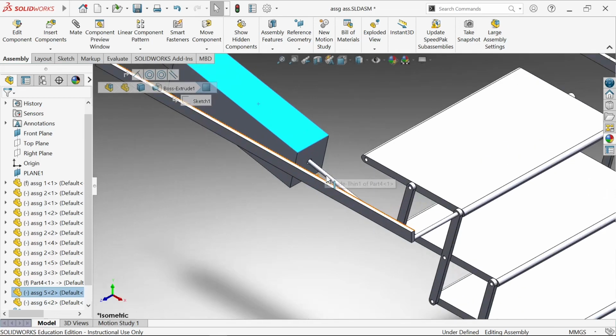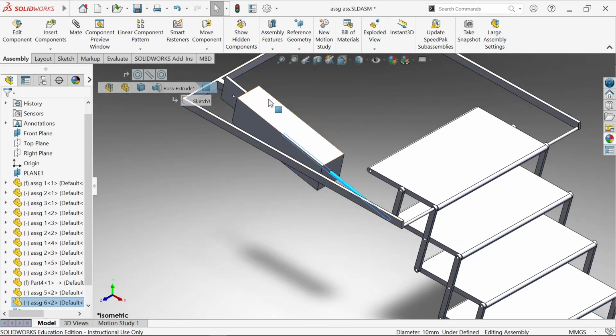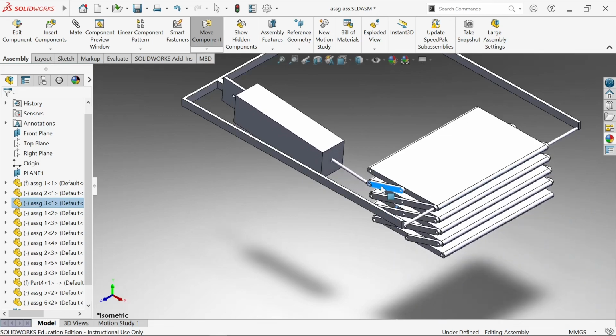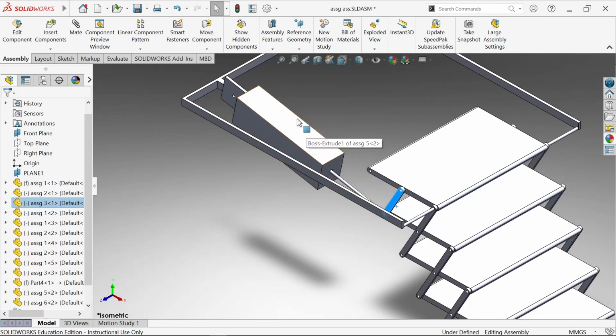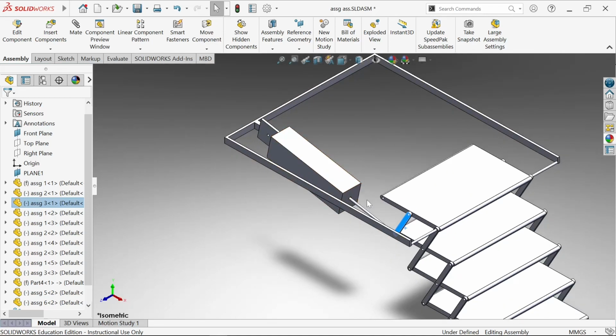And these are the two links that join both the ground link and this driving link. This can be thought of as the coupler, because it attaches on one side to the ground link, and on the other side to the driving link. And this is in the form of a shaft that goes in and comes out of this link, which you can call the hub link, or the hub, which facilitates this shaft.